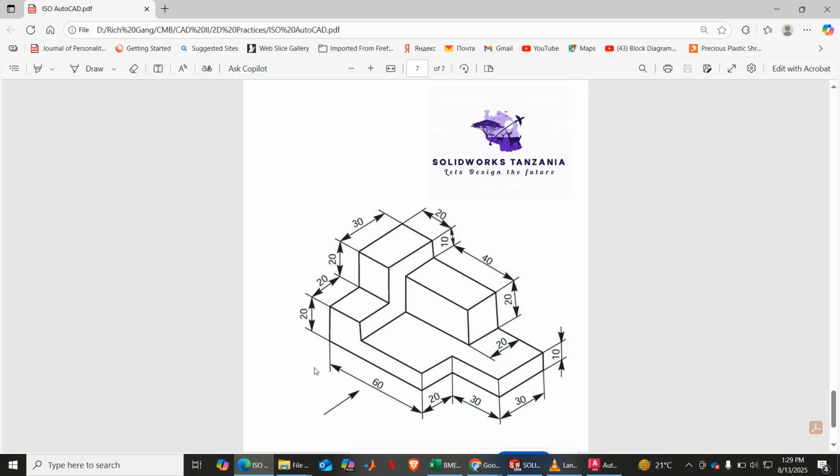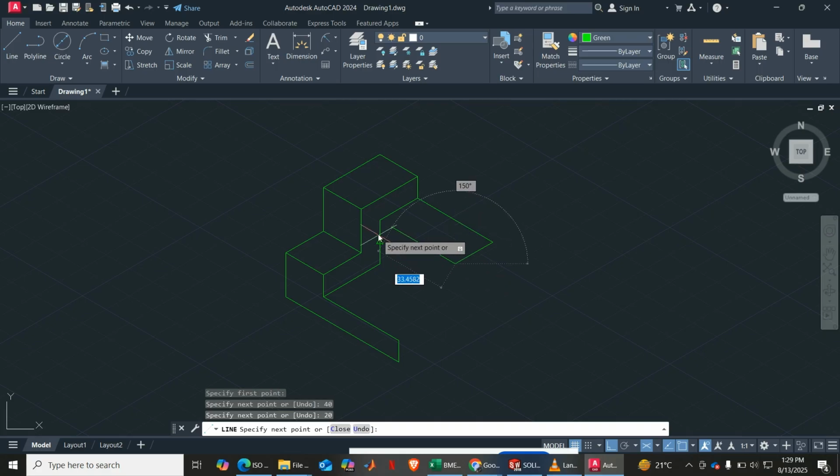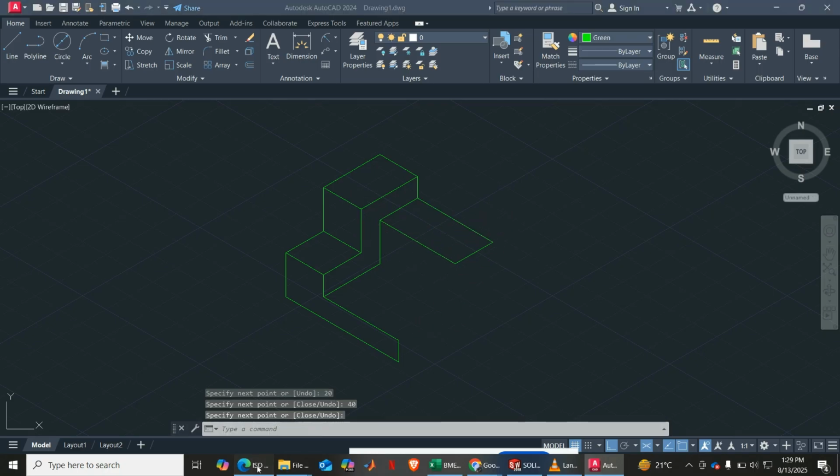Okay, it's almost coming, right? Now you can draw this one here on the top view. So this one here is 40 by 20 by 40, right? So I come here and say Control E, top view. So line from here this way 40, this way 20, and then this way I can click here, or I can just type 40 again, enter, right?